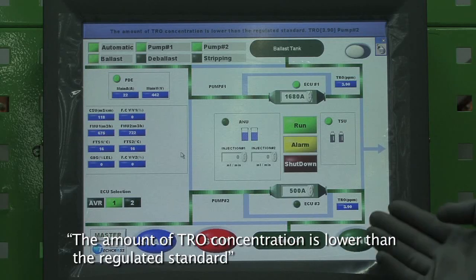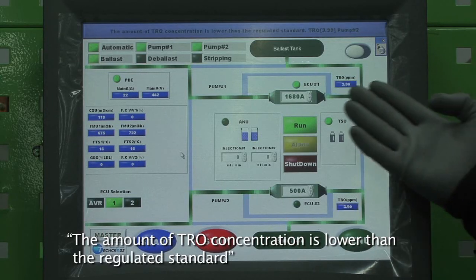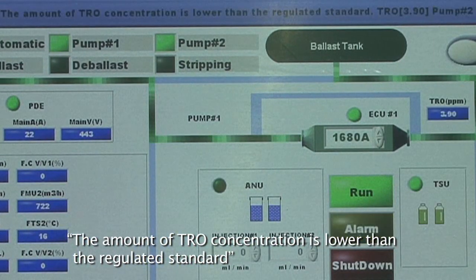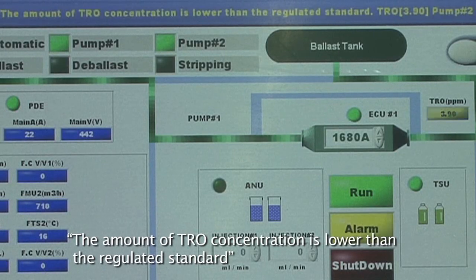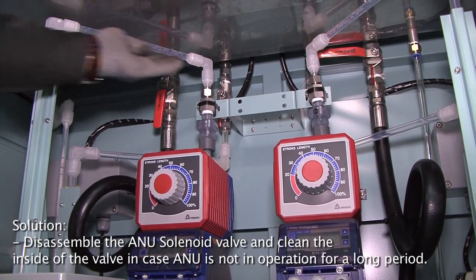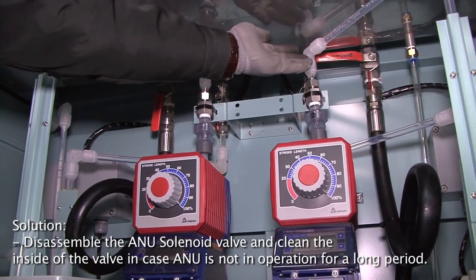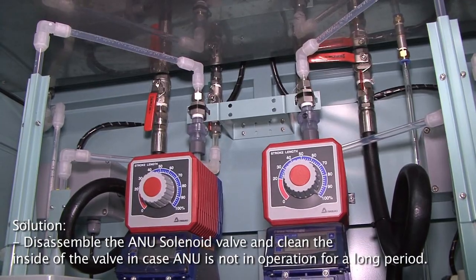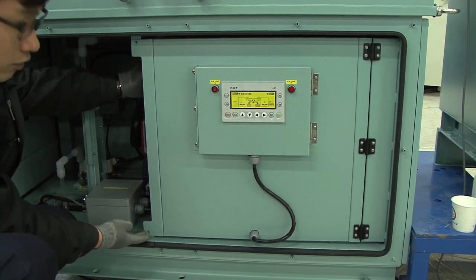Problem. ECS shuts down 10 minutes after alarm message. The amount of TRO concentration is lower than the regulated standard, appears. Reason. When discharged neutralizing solution is not injected to the pipe properly during deballasting operation. When outlet pipe of ANU is clogged up. Solution. Disassemble the ANU solenoid valve and clean the inside of the valve in case ANU is not in operation for a long period. Procedure for maintenance of solenoid valve.